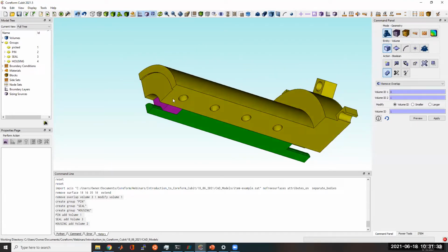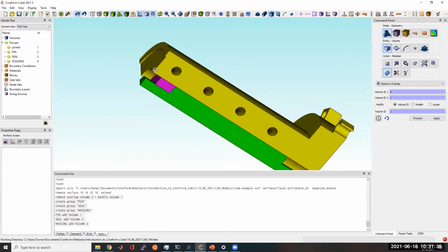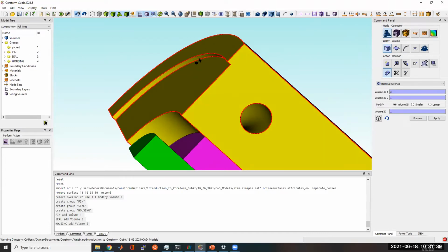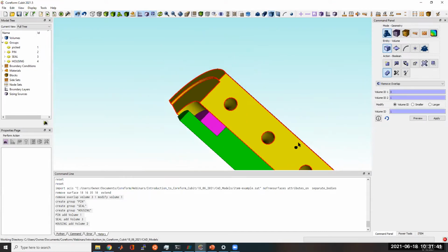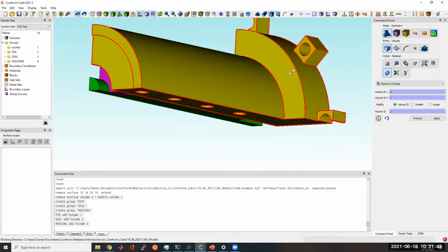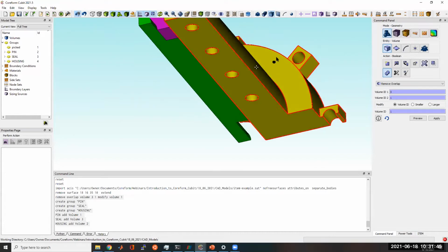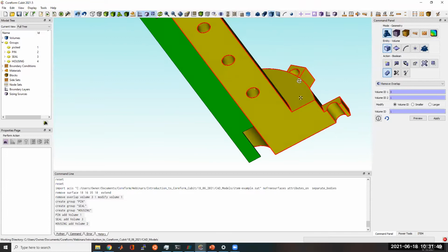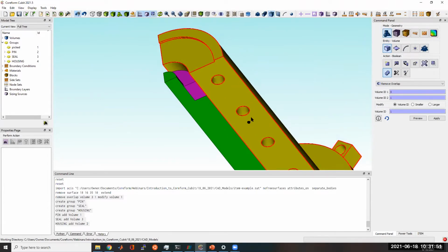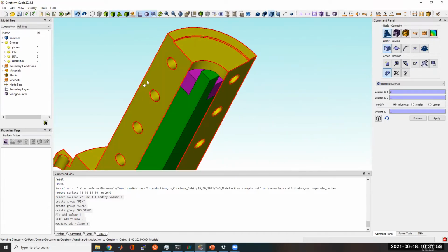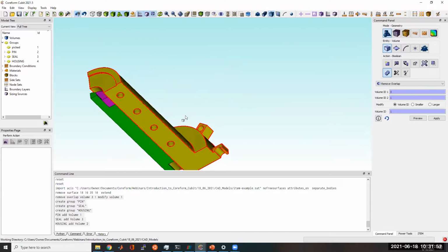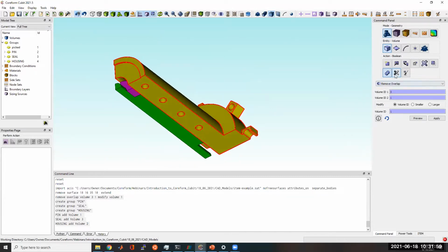So what I'm going to do first is we can kind of see that this little top surface here, I could chop it off and I would get like a rectangle. And then if I chop off this cylinder feature, I'd have an annulus, which is mappable to a cube. And then I could sweep from this surface to this other surface. And so I've kind of mentally broken this down already for how I'm going to do this cutting.